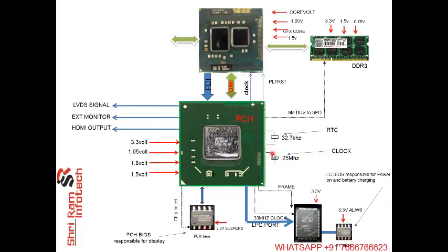Here are the two crystals, one 25 megahertz for the clock and memory controller, another is the RTC. Now this is called the LPC bus, the low pin count bus, which is connected to the SIO. And here you can see there are two BIOS. This one is called the EC BIOS, embedded controller BIOS, and it works on the always voltage.